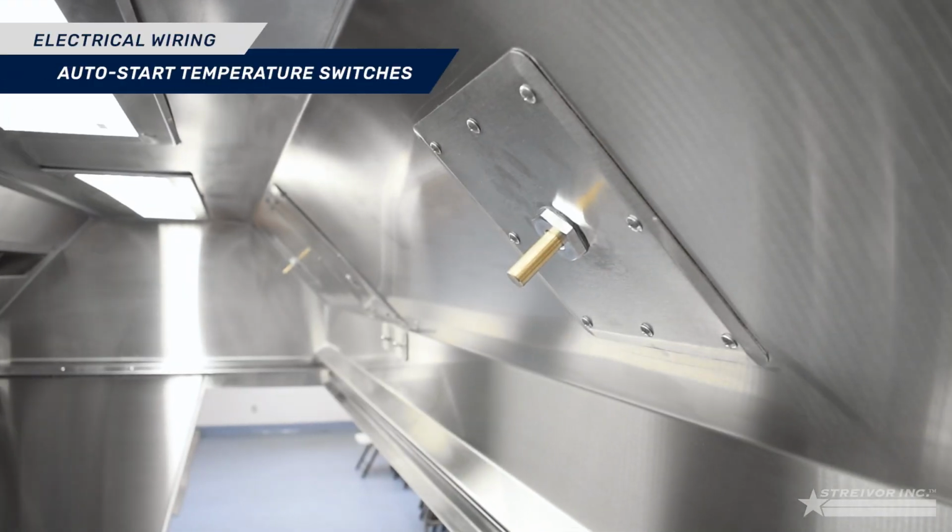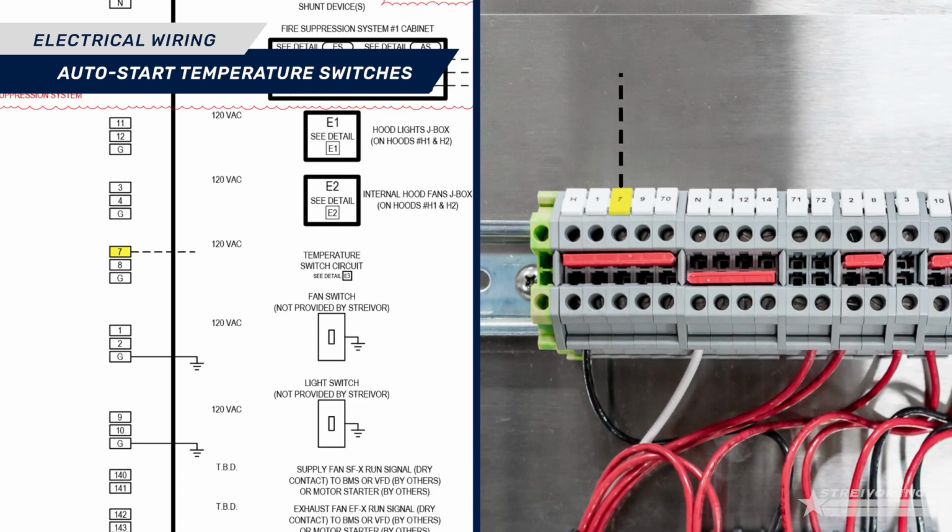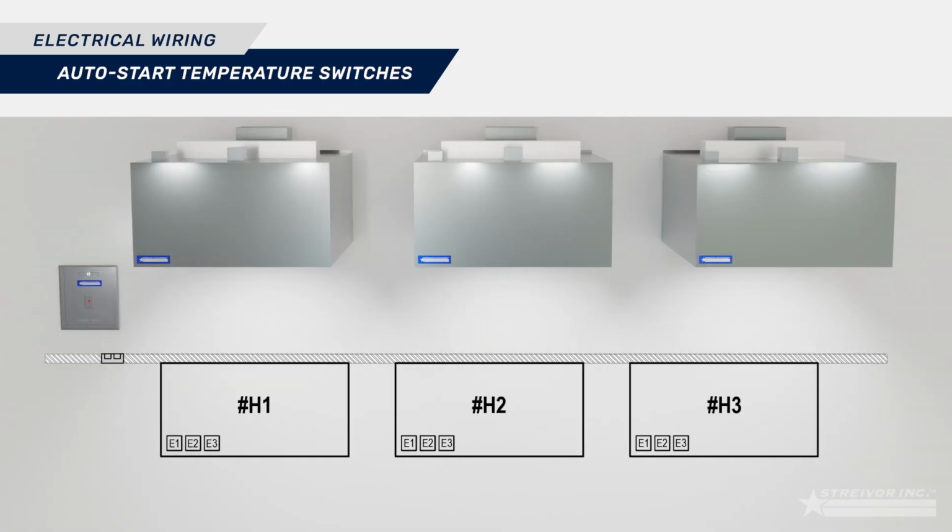To supply power to the auto start temperature sensors, wire terminal block 7, hot, terminal block 8, load, and ground in the control panel, to the wires in the junction box labeled TJ on the hood. If the ECP is controlling the temperature switches on multiple hoods, locate the E3 junction boxes for each additional hood, and daisy chain them together.